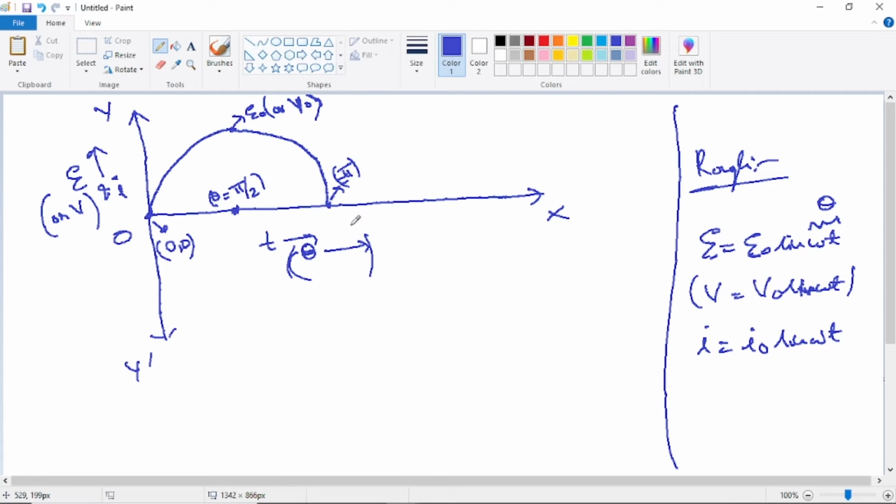Now just see here. Whatever things we are seeing here are simple. Nowhere is any complication there. Now what is happening is, beyond 180 degrees, the EMF, sine theta, becomes negative. Sine values become negative. So EMF, just observe the cursor compulsorily, EMF becomes negative. So the graph goes below the x-axis.